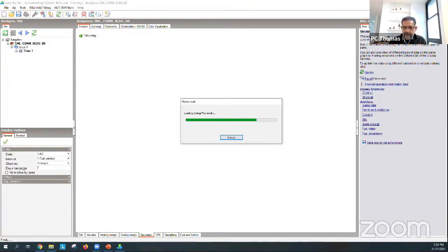Okay, and that during the time when the conditions outside are within certain conditions, then you can switch off the air conditioning and allow windows to open and close as required, or using some explicit control strategy.